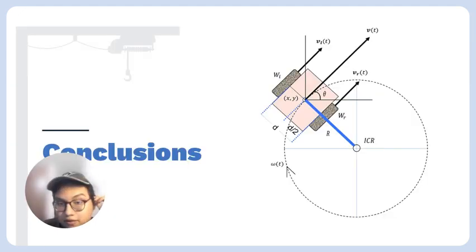For our final conclusions, we can say that the model is a good representation of a differential robot. It combines theoretical aspects of control systems with practical considerations of robot kinematics. It shows an understanding of how individual components like motors, controllers, and kinematics interact within a robotic system. In real-world applications such as autonomous navigation or task-oriented robotics, this model will likely exhibit a good degree of accuracy in path following and maneuverability. The PID controllers, tuned for the specific dynamics of the motors, will ensure responsive and stable control.